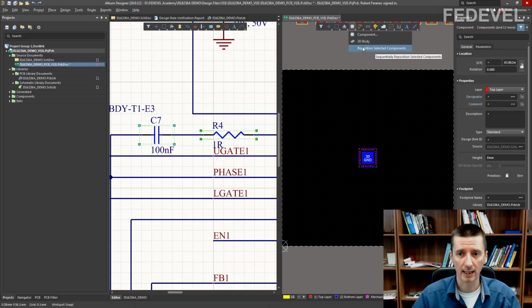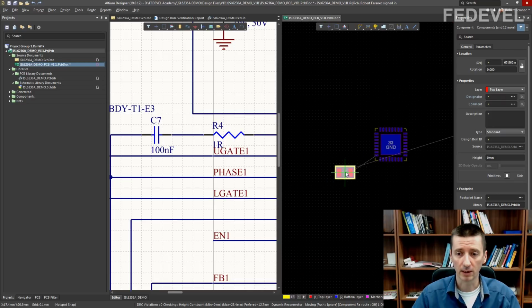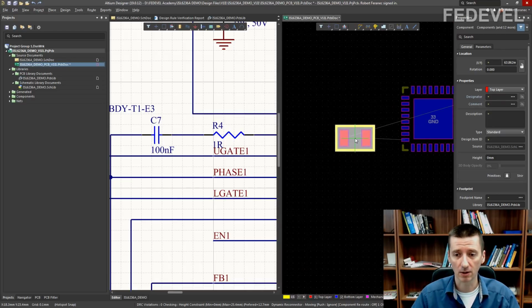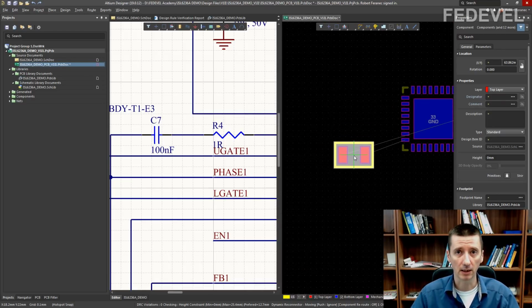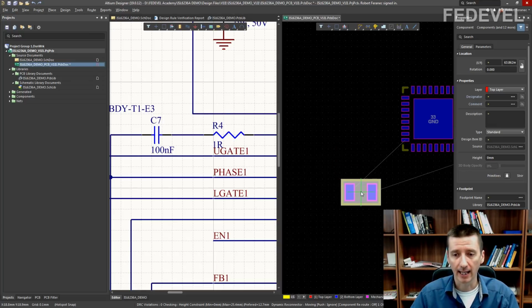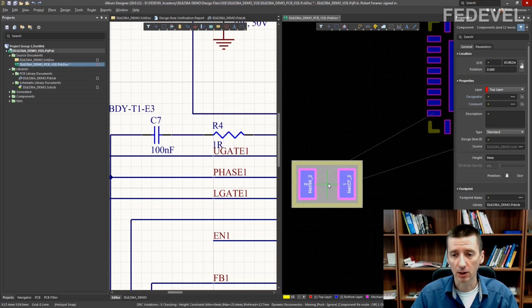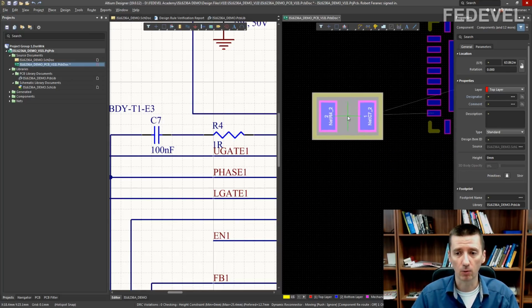So what is going to happen when I click on these reposition selected components? We will be automatically holding the resistor which was selected as the first component. So left click on reposition selected components, zoom in, see we are holding the resistor. We would like to place it on the bottom side of our PCB, so press L on your keyboard and watch the connections, the yellow lines.